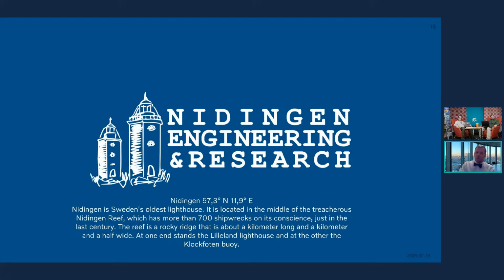So this only does single phase, single species, and you can add some pseudo changing media via this magical property X, which can be concentration, for example, in a glycol water mixture. So don't overdo it. Don't think you can do two-phase change and everything. Make a separate library for that. So keep things simple. Simple is fine.